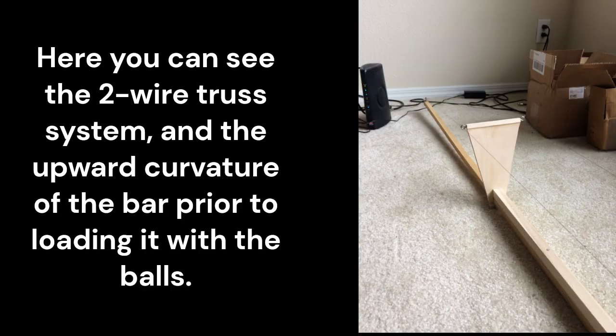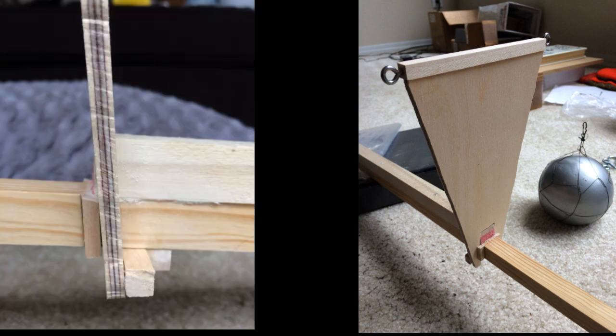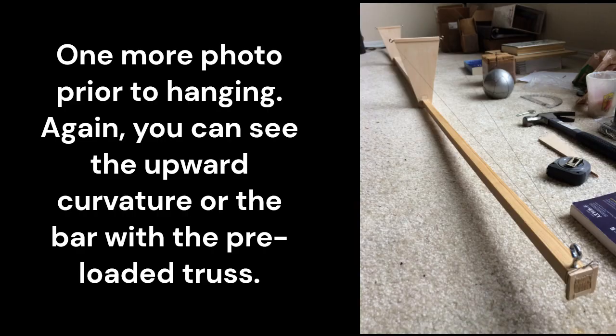In this picture, you can see the 2-wire truss system, and you can see the upward curvature of the bar prior to loading it with the balls. So the truss is loaded up, but the balls aren't hanging on it, so it's got an upward curvature, which is visible out at the end. These are just a few pictures of how this truss strut was attached to the horizontal bar, and everything was done with Elmer's glue and screw eyes. One more photo prior to hanging. Again, you can see the upward curvature of the bar with the preloaded truss.